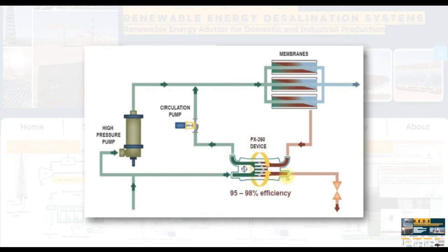The same technique fits for the pressure exchanger device. We can exchange the pressure from the outlet brine with the split feed from the inlet in order to transfer the high pressure from the brine to the feed. Splitting the feed at the inlet will also reduce the pressure on the pump, and so the load or the specific power consumption at the same time.